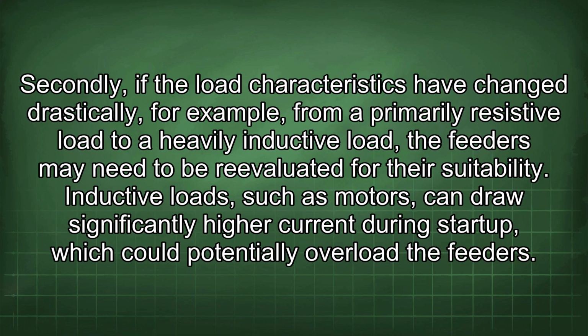Secondly, if the load characteristics have changed drastically, for example, from a primarily resistive load to a heavily inductive load, the feeders may need to be reevaluated for their suitability. Inductive loads, such as motors, can draw significantly higher current during startup, which could potentially overload the feeders.